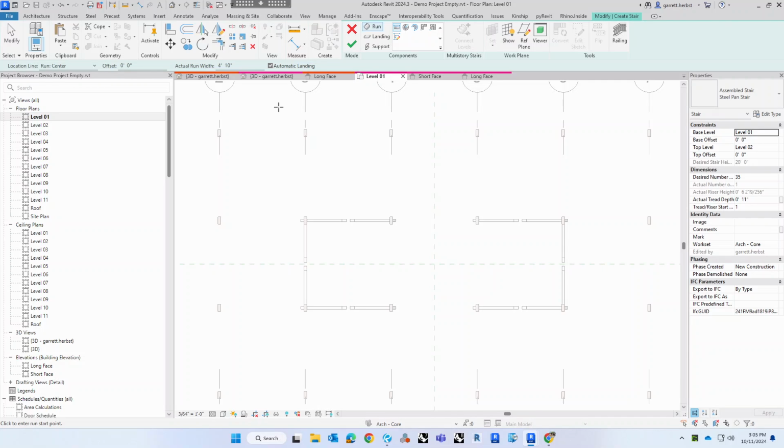However, it is floor to floor, so you don't have to accumulate all of the floors. It's really just floor based. And so, rule of thumb that we typically use: a 5 foot wide stair can accommodate 250 people. So 2 stairs, 250 for each. We can max 500 people on a floor, and that is the max you can do for a 2 stair situation.